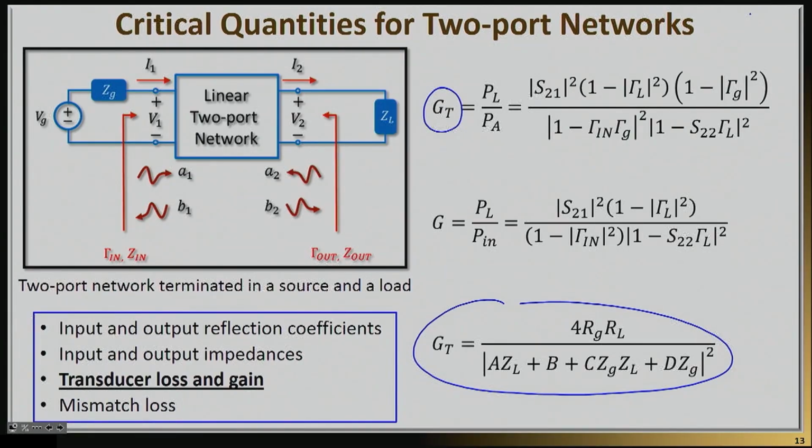Some people will also define the actual gain of the system, meaning they will compare the power that goes to the load to the actual input power, not the available power. And I'm giving you the equation here as well. But in my opinion, and in most people's opinion, the transducer gain is a far better metric than the actual gain, because the actual gain depends on how good of a designer you are, while the other one is a far more realistic comparison.